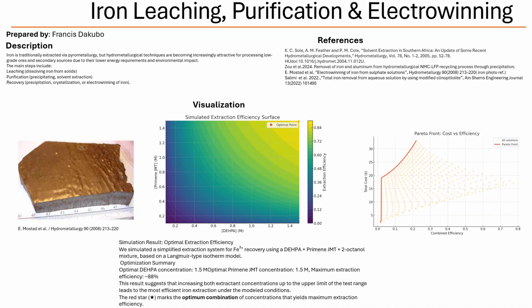Impressive. Okay, let's wrap up our deep dive with those alternative methods for iron elimination using precipitation. We've already touched on the goethite process, but the sources also describe the jarosite and hematite processes. Right. These are especially important in zinc production, where removing iron is essential for maximizing zinc recovery. Jarosite precipitation is all about forming a basic iron sulfate compound. It's stable over a range of pH and temperature conditions, but ideally you want it around 95 to 100 degrees Celsius and pH 1.5 to 1.8.